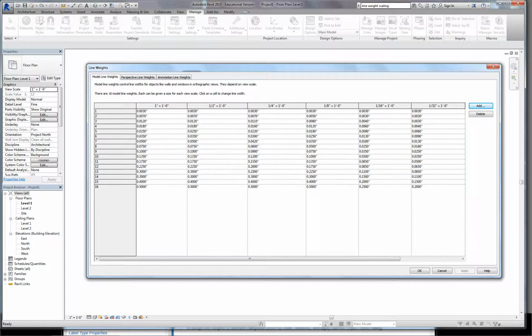So how does that relate to this? Well, these numbers are what's being referenced ultimately in the object styles. Typically, they're set fairly well, in the sense that you probably don't have to manipulate the sizes here that much. It's more about picking different model lines. But if you were setting up your own standards, like you might set up annotation standards, you'd probably spend a day testing line weights, especially for a project that you might use for a whole or use again and so forth.